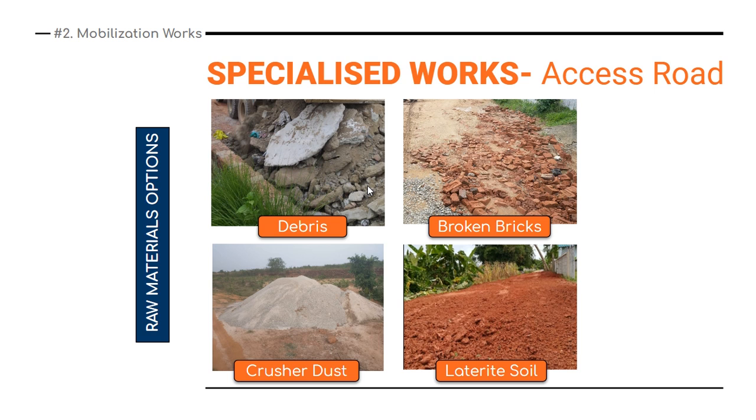Then it is broken bricks. You can collect it from local red brick chimneys. Then crusher dust. This is the most effective way. This is amply available from the nearby crusher area where the boulders are crushed into 20 aggregates or 40 aggregates. Then the laterite soil, if it is amply available nearby your site, or any kind of laterite soil you can use for backfilling purpose.